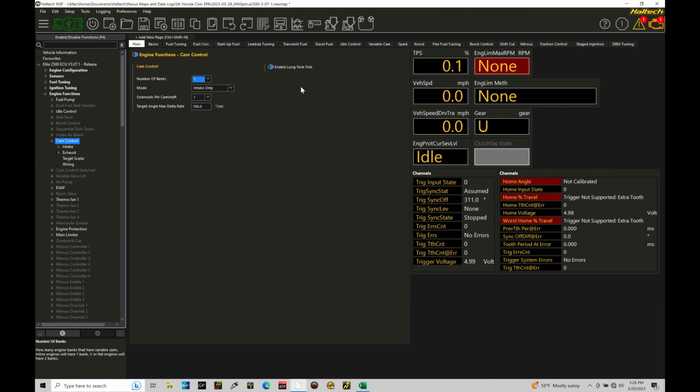This allows the variable cam control to learn what's going on in the short-term adjustment. We'll explain this in a little bit. And then it's going to store it to a background table, and that will allow it to have a modifier against the base duty table so that you have a corrected beginning base duty. So when it's making its short-term adjustments in the closed loop for the variable cam control, it's going to be more accurate and more repeatable, so you essentially hit the desired target variable cam movement that you're programming. Again, this will make a little bit more sense, but we usually want to leave enable long-term trim on here. Okay, if we jump down here under...